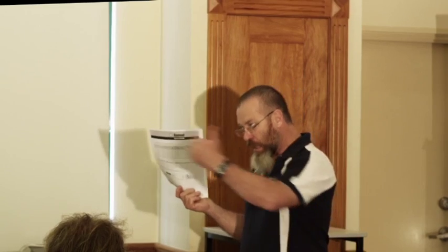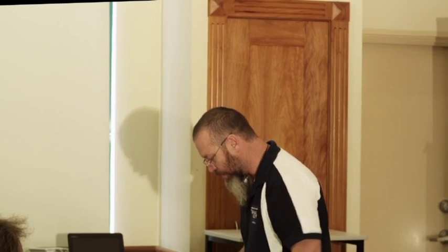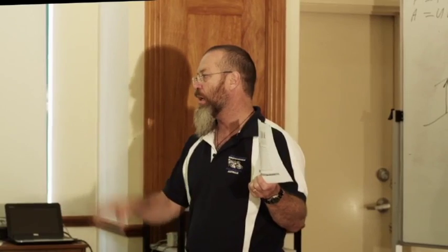manufacturer's installation instructions. You blokes have got to get used to using them. If the building did blow away, the first thing I'd do is go on site and have a look at what he's used to tie the slab down with. And if it was Dynabolts, in this case it happens to be Ramset, but whoever supplied the fixings, I'd get the manufacturer's installation instructions. Again, get used to it. You should be looking at the night before the flooring's going down, you need to go onto the net and download the manufacturer's installation instructions for flooring.